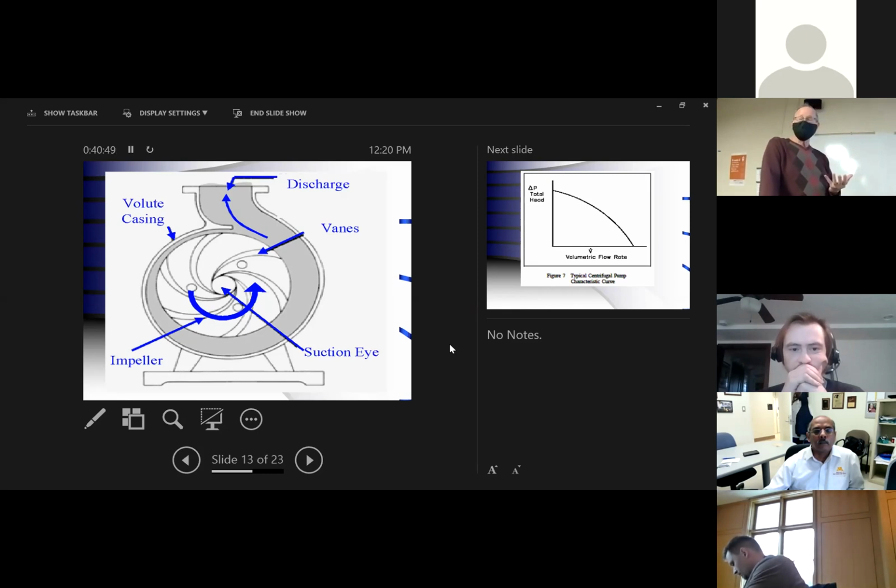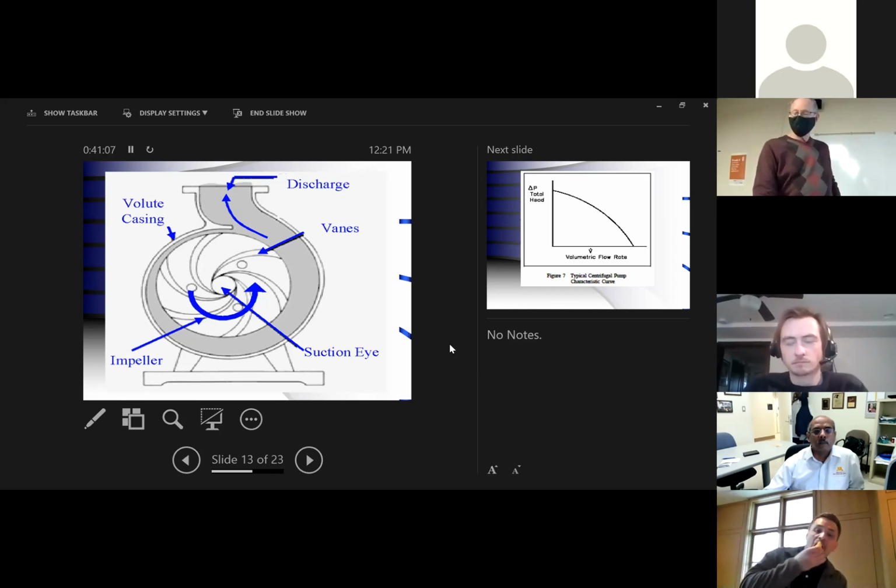With 3200s, very often people will swap one pump out for another pump in cleaning systems, because you want high speed, high turbulence for that scrubbing action you get when you run your product through the pipelines. So that chlorinated alkaline cleaner that you're using is doing the job that you want it to do.